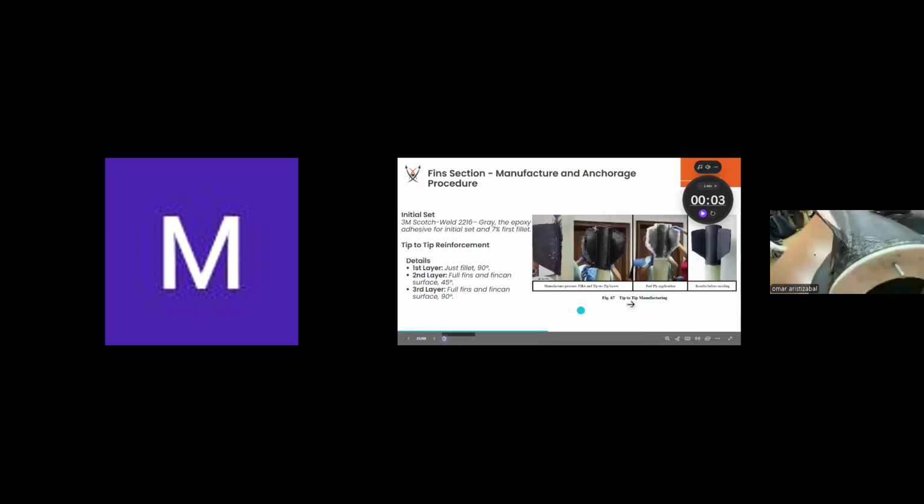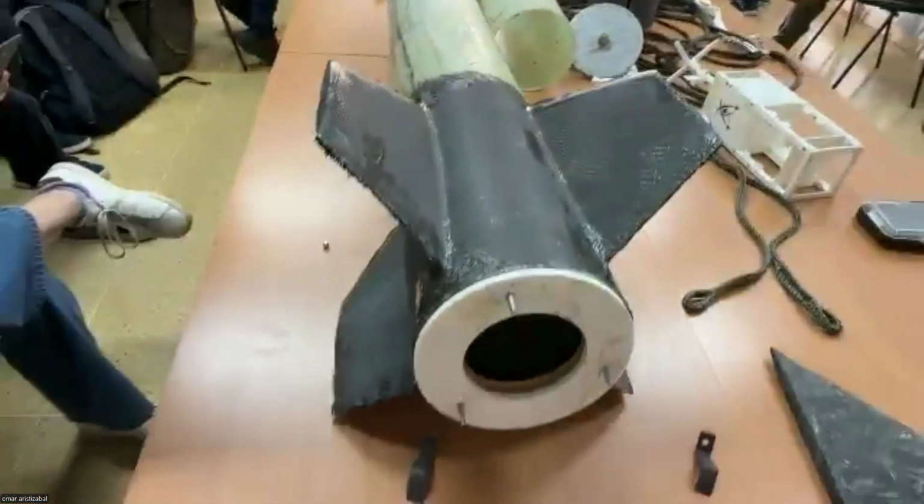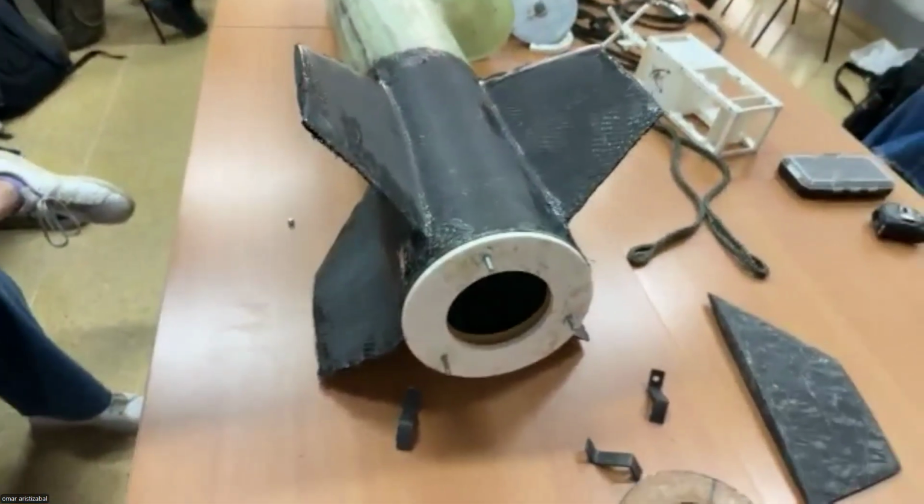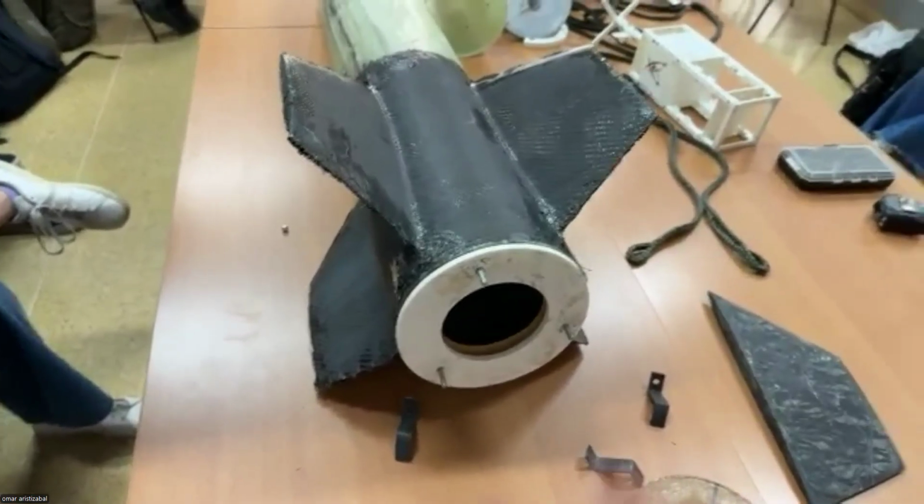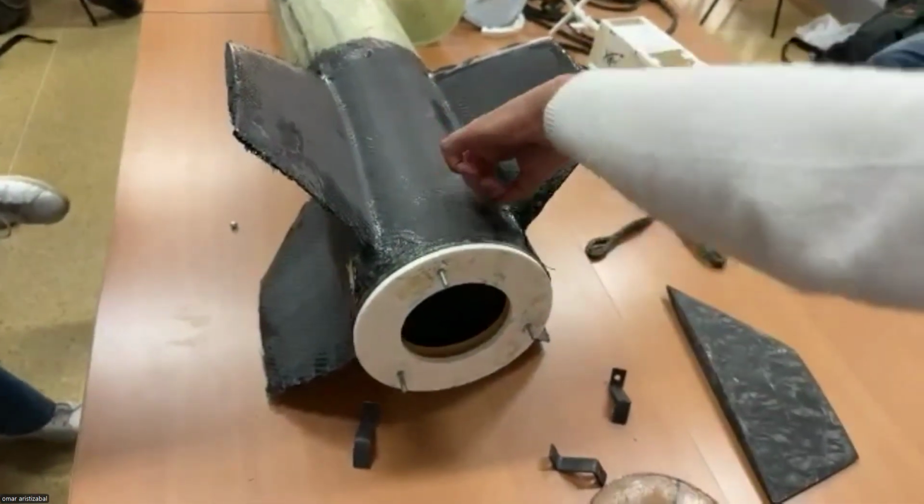These are the fillets. We made them with a 21 millimeter radius, and we used the same aeronautic grade epoxy adhesive that we showed you that we will be gluing the nose cone metal tip with. Okay. And then when you kind of roughhouse it, does it feel firm? Yeah, it does really feel very firm.